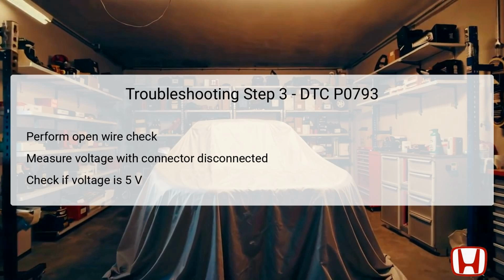Specifically, check the voltage between test point 1 at the CVT drive pulley speed sensor terminal number 3, yellow-red, and body ground. The expected reading is approximately 5 volts. If this voltage is present, the circuit is functioning correctly, and one would move on to step 4. However, if the voltage is absent, it indicates an open in the VCC1 wire, requiring immediate repair or replacement.